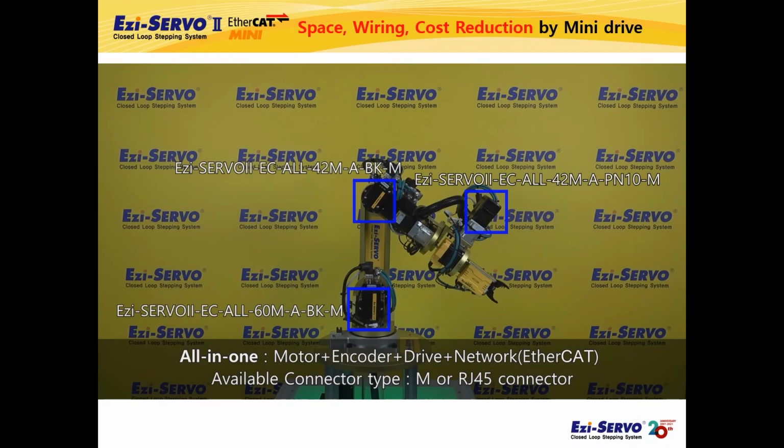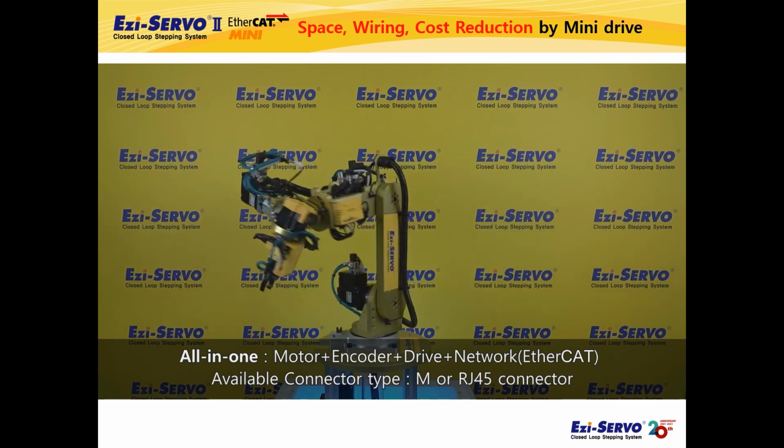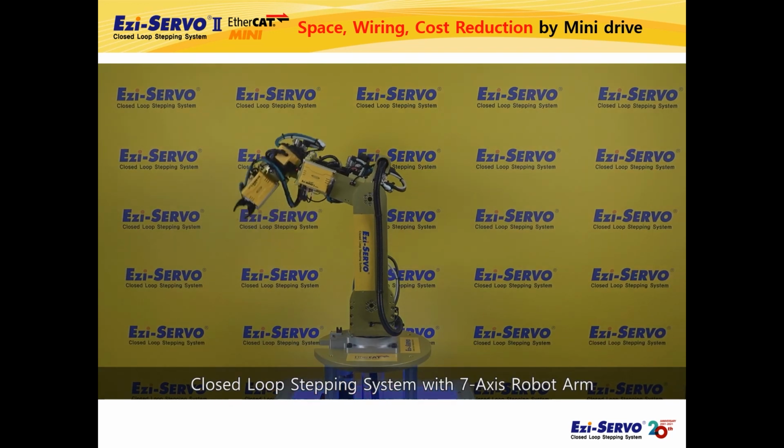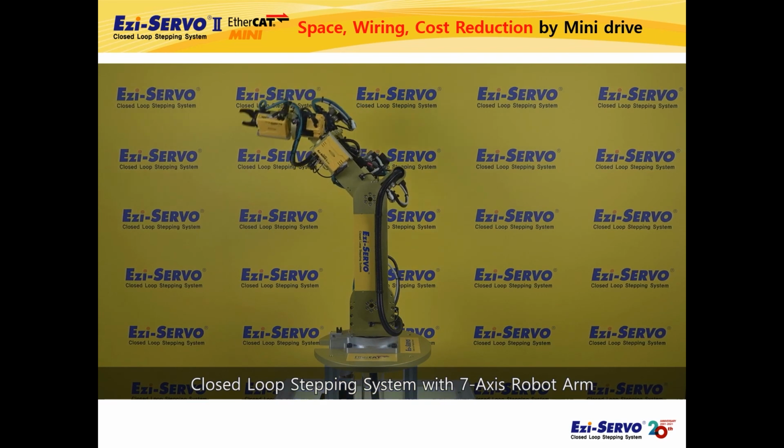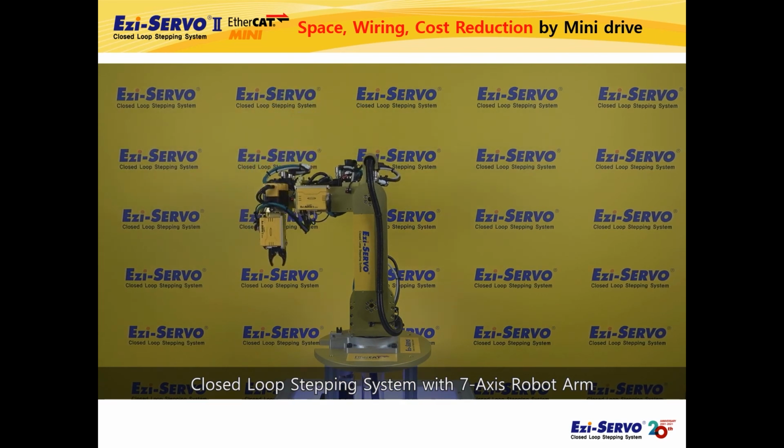In addition, there is no need to wire a motor and an encoder because an Ezi-SERVO II EtherCAT, an all-in-one product that combines a motor, high-resolution encoder, drive and EtherCAT network, is applied to 5 out of 7 axes. Therefore, when using the mini drive Ezi-SERVO II EtherCAT Mini and the all-in-one drive motor, there is no need for a separate control box.